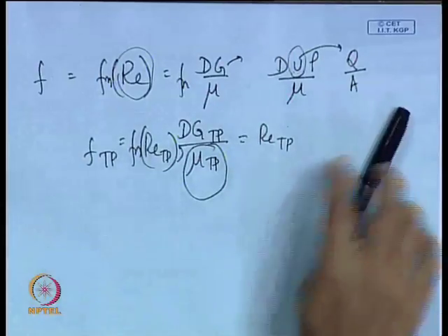Because for density we can very well say that it is a function of the component densities as well as the void fractions, or the volumetric proportion of the two phases inside the flow. And since it was a no slip condition, the volumetric proportion with which we had introduced the flow was equal to the volumetric proportion with which the two fluids were flowing inside the pipe. With what volumetric proportion we had introduced them into the flow is already known to us. What we cannot control is what will be the proportion inside the pipe. For homogeneous flow, they are the same. So, finding out rho was no problem.